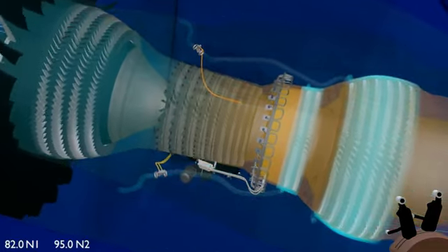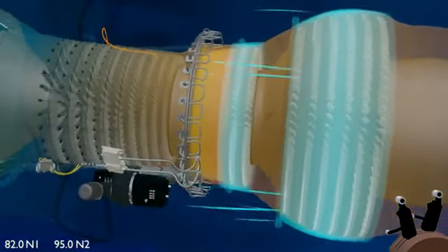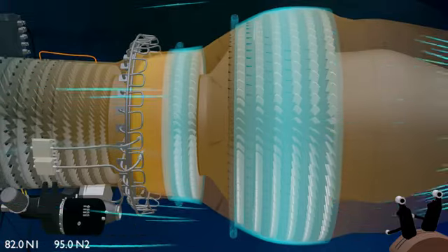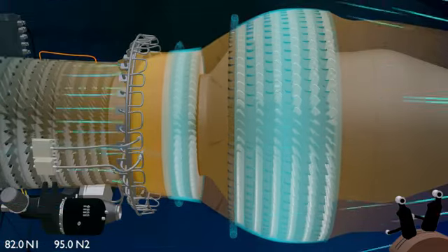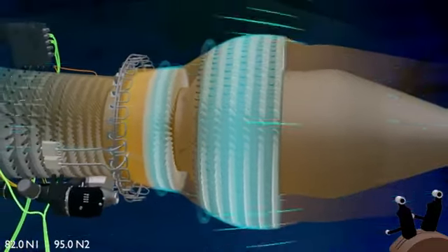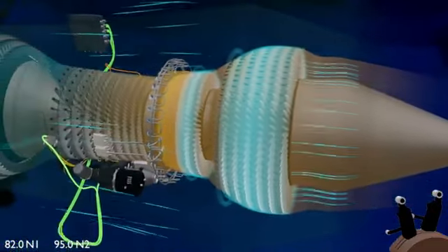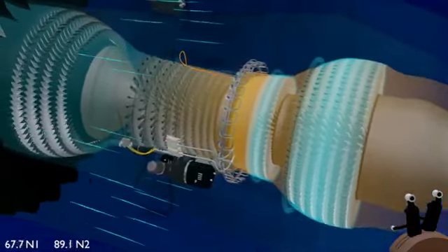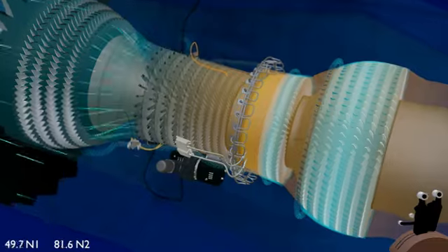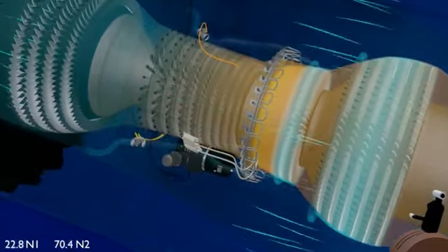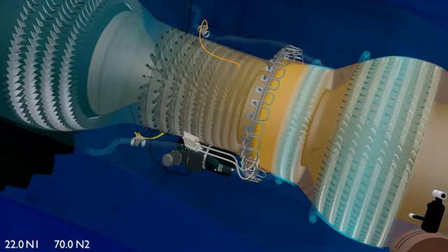The circulation in the manifold cools the turbine casing, reducing its temperature and thereby decreasing the thermal expansion. This keeps the tip clearance to a minimum, giving higher power for the fuel burn. Both the valves give their position feedback to the EEC. Reducing the engine speed drops the temperature in the turbine section, therefore the valves are moved to a more closed position, but are never fully closed, ensuring limited airflow continues to cool the casing at idle speed.